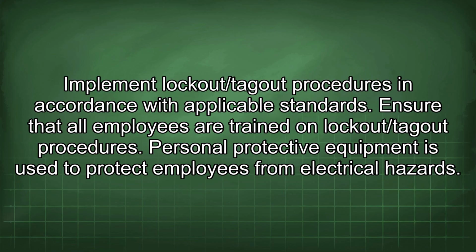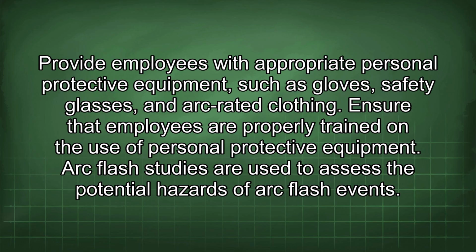Personal protective equipment is used to protect employees from electrical hazards. Provide employees with appropriate personal protective equipment such as gloves, safety glasses, and arc-rated clothing. Ensure that employees are properly trained on the use of personal protective equipment.